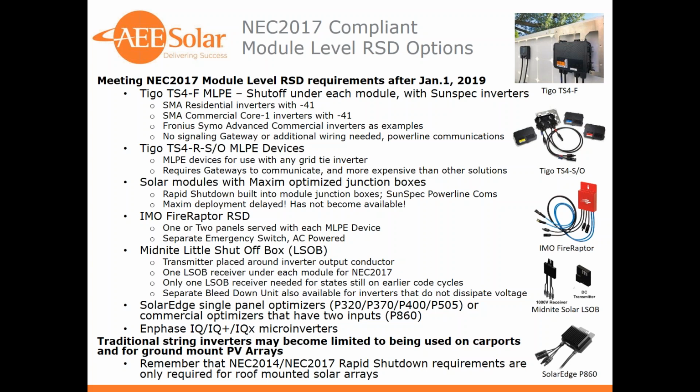Other options which one could potentially consider, the IMO Fire Raptor. So we have 2 module inputs. You could do up to 2 modules to that device. That does have some of the same downsides that we talked about. We have to worry about cold state conditions. It is a more expensive device as well, and also requires a separate emergency shutdown switch and control wiring to each of the shutdown devices.